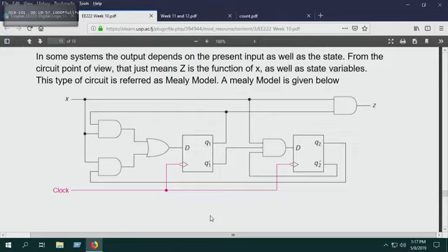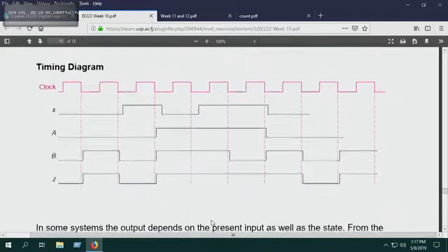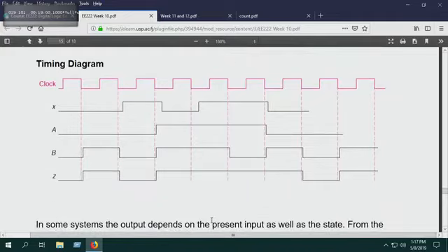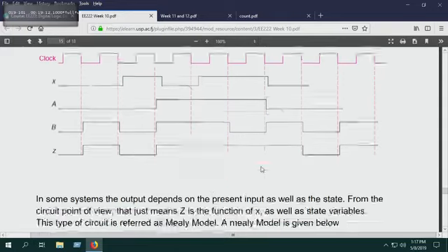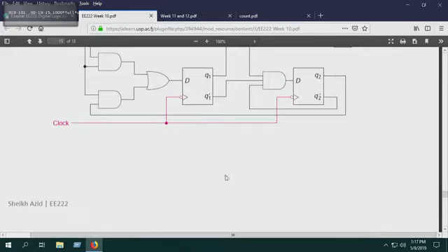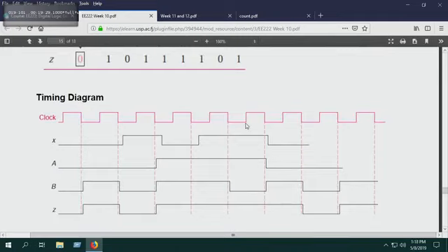Okay. Now, there's something else called the timing diagram. Nothing too difficult about the timing diagram, right? All you got to do is, when the clock triggers, if it's a negative edge or positive edge, there's a particular edge. What do we mean by edge? Let's have a look at it. Over here, can you see there's a bubble in front of the clock? That triangle over there indicates a clock. If there's a bubble, that means it's a negative clock. Negative edge means falling edge, when the clock was falling.